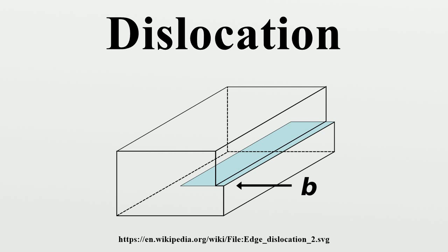Dislocation geometry. Two main types of dislocation exist: edge and screw. Dislocations found in real materials typically are mixed, meaning that they have characteristics of both. A crystalline material consists of a regular array of atoms, arranged into lattice planes. One approach is to begin by considering a 3D representation of a perfect crystal lattice, with the atoms represented by spheres. The viewer may then start to simplify the representation by visualizing planes of atoms instead of the atoms themselves.